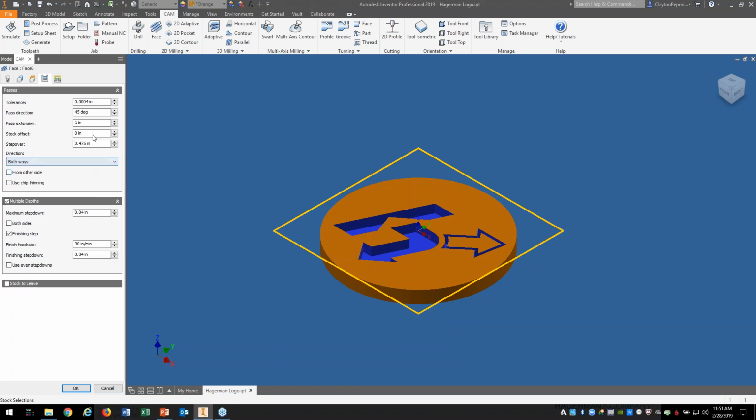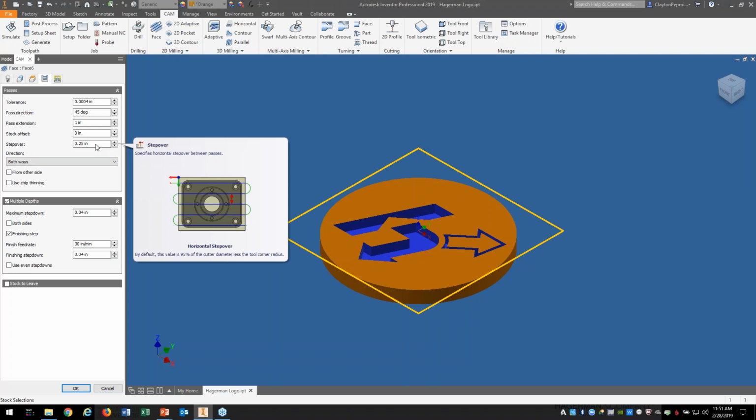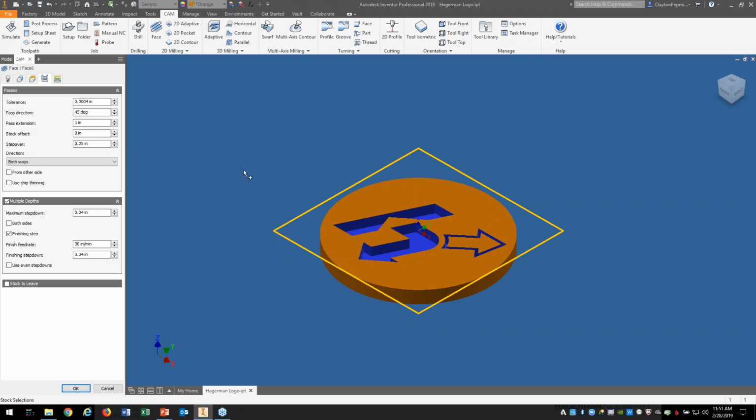So just to give you an example. There's the built-in default. There's my default. Factory built-in, 95%. Mine, 50%. So even though there's expressions in there, if you take a look at them, chances are you can set your default. By using an expression, I now have a default there that's going to work with any size tool I pick up. So my point is, why not set these to your preferences, and then you'll be able to go crazy on every toolpath and not have to really edit anything.